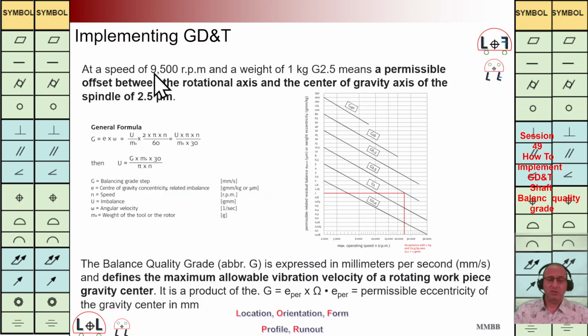Normally, 9,000 or 10,000 RPM is really fast, I can say. Between 10,000 RPM to 20,000, 25,000 RPM, it is really fast. In some CNC machines for finishing, we have that higher speed. Between 6,000 to 10,000, I can say they are at the medium level. But in normal industrial applications, the RPM is less than 6,000. However, for this example, it is 9,500.